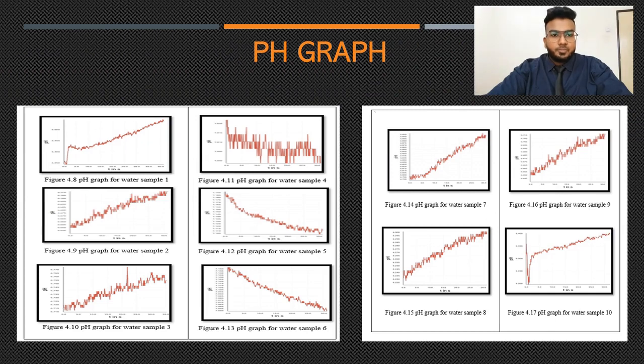The pH meter was calibrated before starting each testing to avoid errors in the reading. The pH value for the flood water is 5.81 and the turbidity of the flood water is 130 NTU. A pH value of 7 is regarded as neutral. The ideal pH value for drinking water is between 6.5 and 8.5.